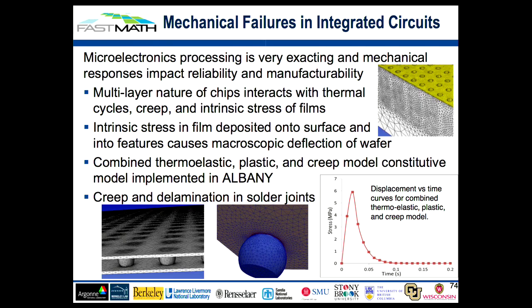This happens at high temperature, so you can imagine that when the material cools down, the metal and the silicon contract at different rates, so you can have very, very high stresses. In fact, a lot of chips need to be thrown away because of structural failure. So it's interesting to simulate this numerically and see if there are ways to mitigate this issue.